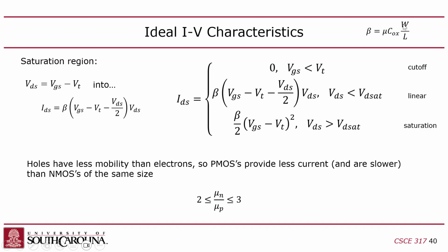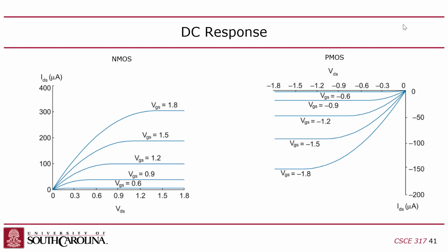So the PMOS transistors have double the width, same length, but double the width. If you look at a layout, you'll see that the PMOSs are usually twice as tall as the NMOSs if you're looking down on the mask, on the design. Okay? Oh, shoot, I'm out of time. Any questions about that?